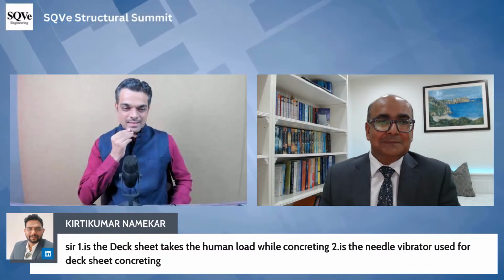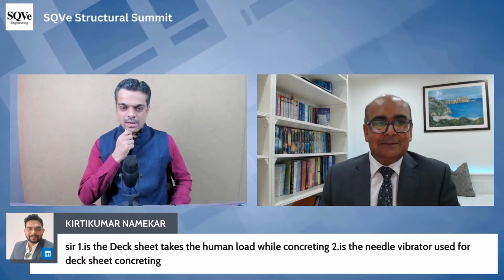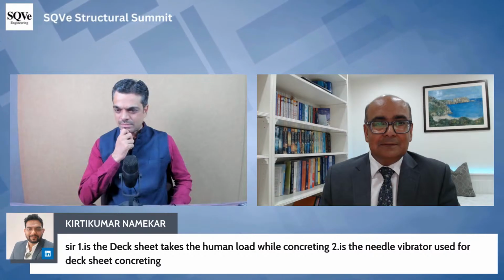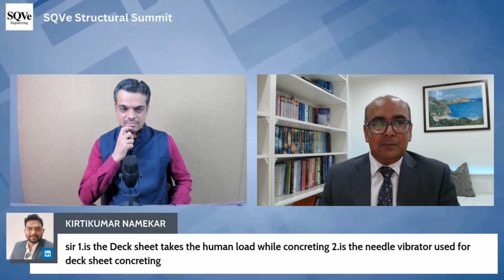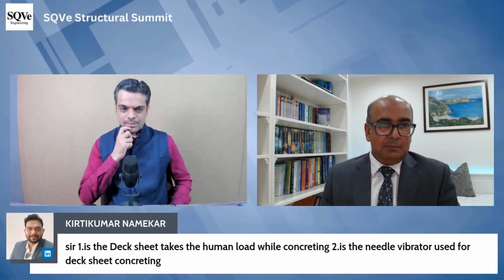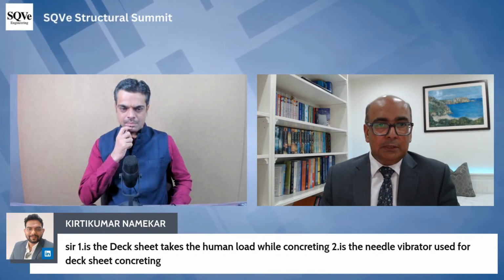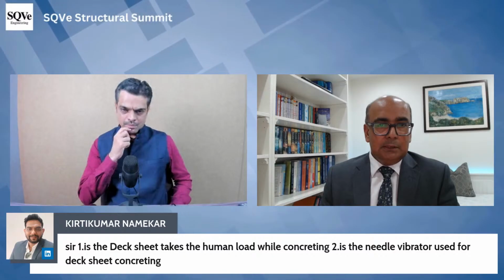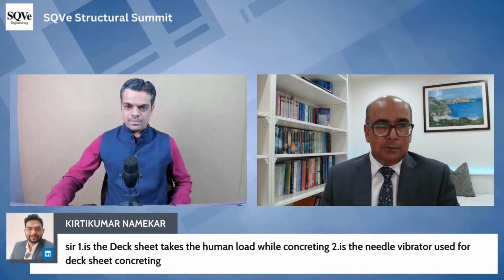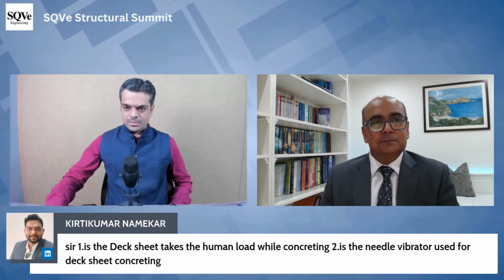Kumar is asking whether the deck sheet takes the human load while concreting, and second, is a needle vibrator used for deck sheet concreting? I haven't seen a needle vibrator used for deck sheeting, but it might be used. And human loading while concreting, yes, because we take this workman load of 0.75 kilonewton per meter as live load. Yes, it does.